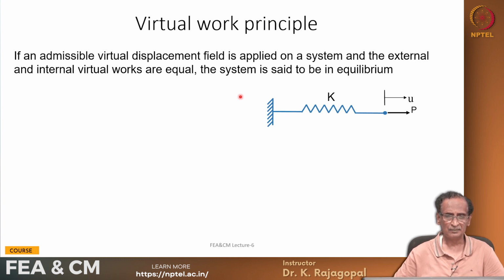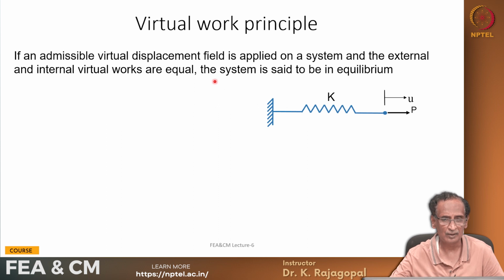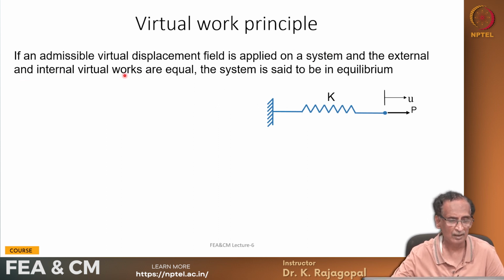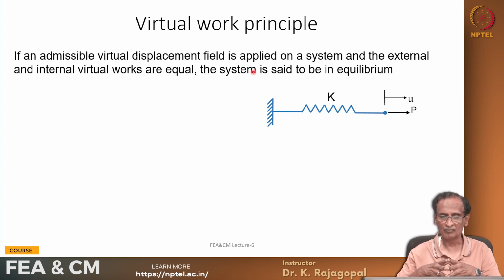Let us look at one of the oldest principles, the virtual work principle. If any admissible virtual displacement field is applied on a system and the external and internal virtual works are equal, the system is said to be in equilibrium.